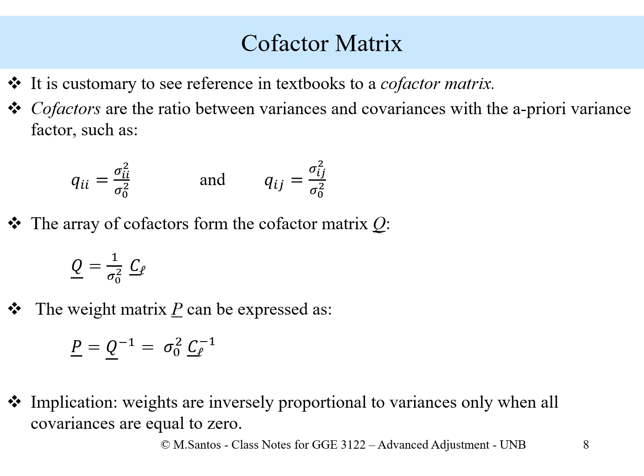Okay, so then the weight matrix, which is what we usually use in the adjustment computations, will be, as a matter of fact, the inverse of the cofactor matrix.